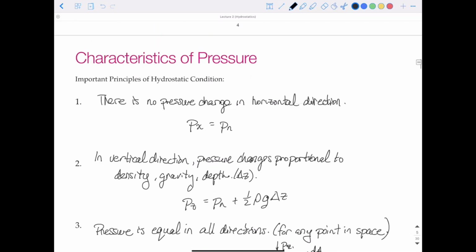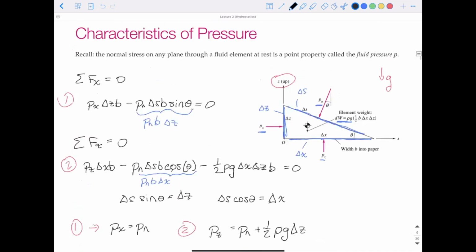The analysis above, we just chose a wedge. If we think back to our solid mechanics course and we wanted to find internal reactions, internal forces, and we derived the equations from Mohr's circle, we basically did the same thing. So we have our stress in the X, stress in the Z, and then we have our wedge. We wanted to figure out the stresses. For a solid, we wouldn't just have this normal internal force. We would actually have a shear force as well, right? So for a solid, we would have some shear component also acting on that wedge.